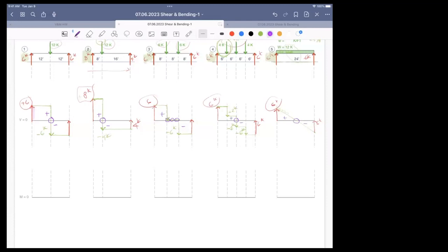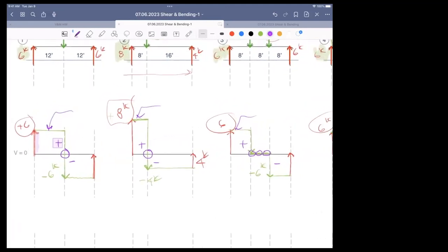So if your shear diagram is constant, your moment diagram will be sloped. If your shear diagram is sloping, then your moment diagram is 1 degree higher. This is all calculus. It'll be a curve. So I see a positive area, and it looks like the area in the shear diagram is equal to the moment. So what I have to do is basically calculate this area, and that'll be it, because I'll reach 0 shear. That will be the maximum.